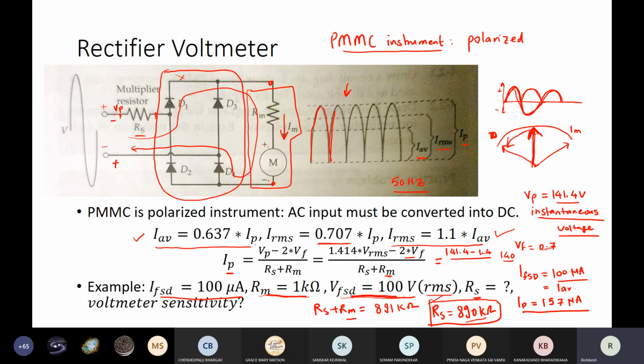So in order to ensure that even at low voltage the diode will be properly forward biased and the voltage drop across it remains 0.7, as used in the calculation of the component values, we need to make sure that a certain amount of current flows through the diode.